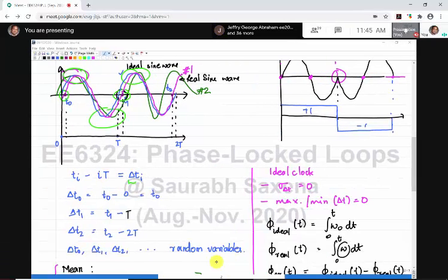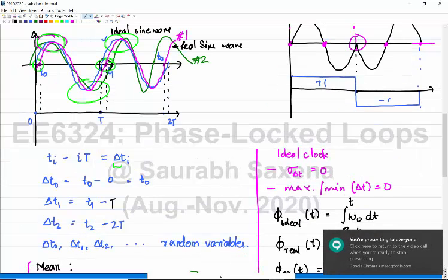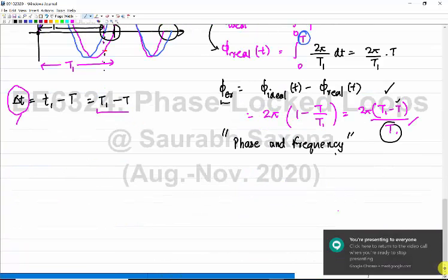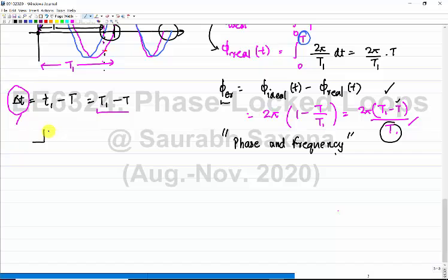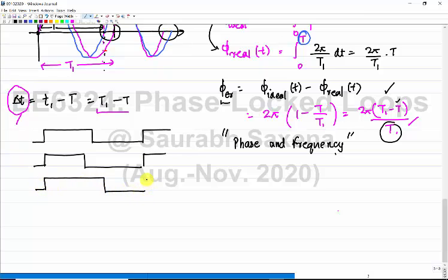So, in some cases, it is still shared, right? What happens is that in some kind of clock signals, you may have, let me just draw a square wave. Whether it's a sine wave or a square wave, I can just draw this clock period, right? I may have this, another, maybe I have this. When you are generating a high frequency clock, you can have all such kinds of options. So here, all the rising edges are aligned, but falling edges are not aligned. And this is normally called duty cycle error.